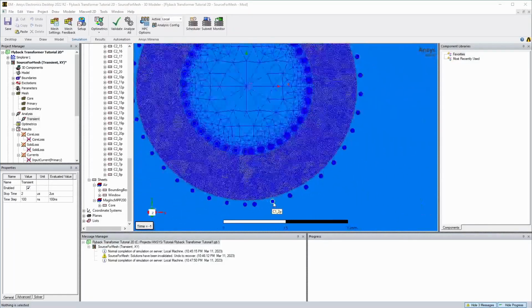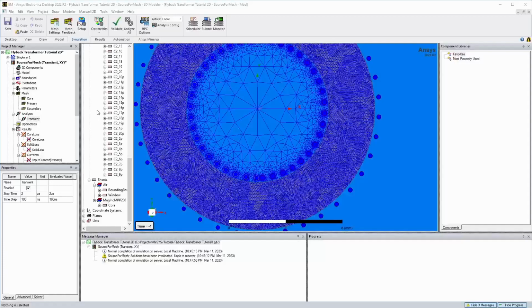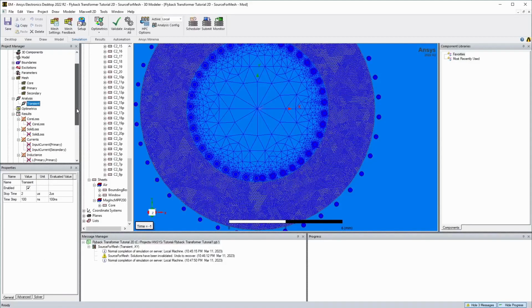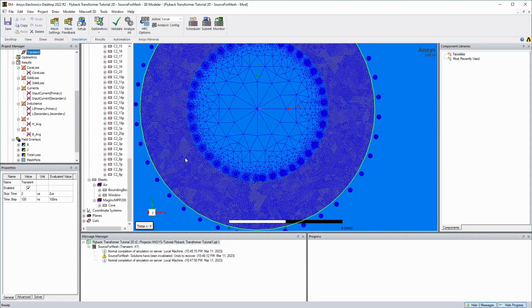And the mesh, it is a little tricky to see if it worked or not. So I think the lesson there is just make sure that you get rid of the analysis. If you have one already generated, just revert to time 0. And that way, I said before that you can't see the mesh unless you're at a certain time. And I guess that's sort of incorrect. So you can at time -1, which is like before anything ran, you can see the mesh. I guess maybe only if an analysis hasn't been run or something like that.